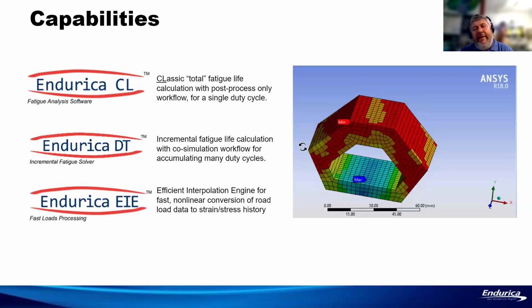You can do an infinite life analysis with CL. It's just a post-process type of workflow. So you would run ANSYS, and then you would run Endurica, and you'd get a fatigue contour. That's kind of an example of what it would look like to use CL.